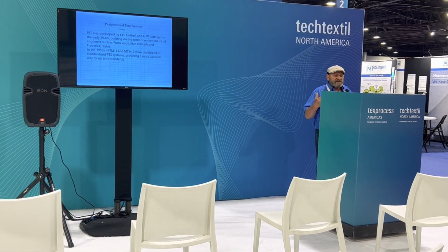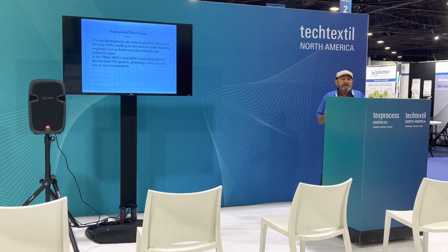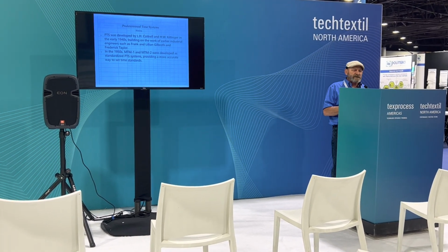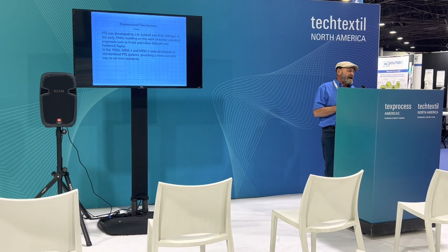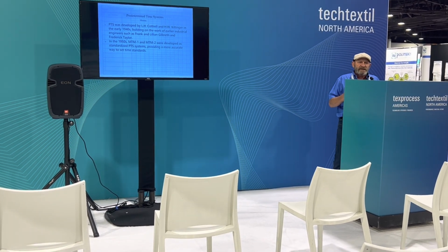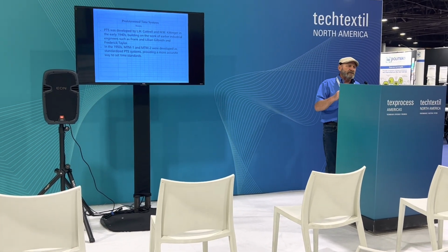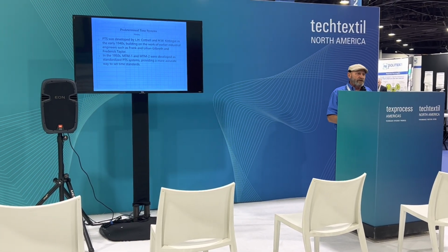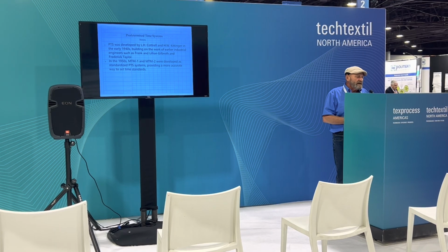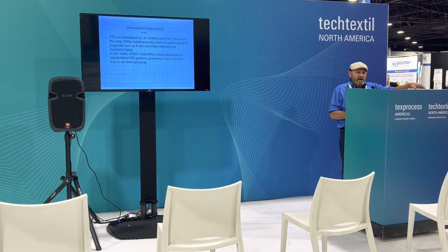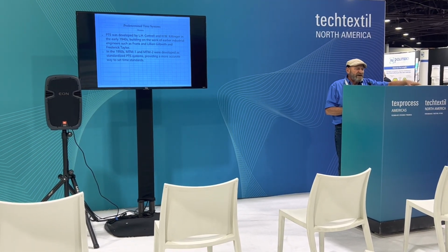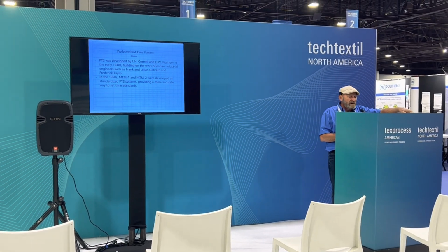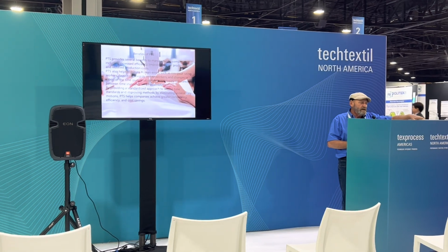So then the next system that came along was MTM2. They were trying to reduce the number of codes and make it easier to apply, make it more practical to use in a manufacturing environment. What they did was combine these codes together to make only 2 codes out of about 5 or 6, which became known as your gets and your puts. MTM2 is a very precise system to use for setting production standards.